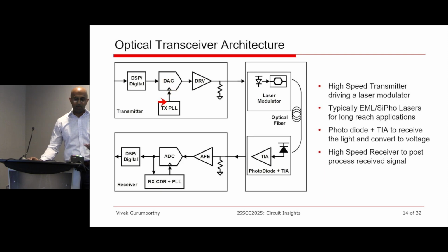This is where some of the details that Kevin gave in his talk were very helpful. Think about the single bit response that he was talking about. That applies everywhere, not just in wireline. Even in optics, a single bit response is pretty important, and you need to have a clock reference in order to convert the digital into an analog voltage. And then we drive that out to the laser. Now we are modulating the laser. It goes through the optical fiber, however long you want to send it, based on different types of lasers.